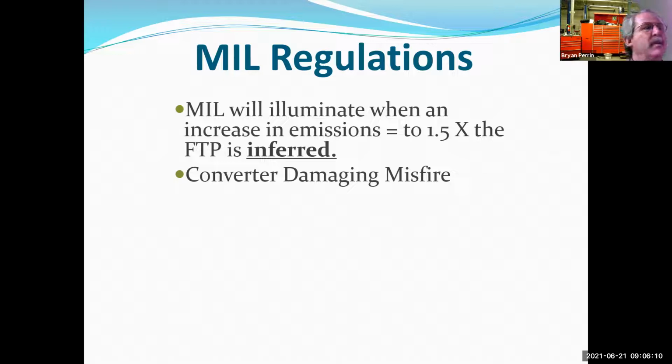So, I have a catalytic converter that melted out. I just ran across a piece of it. It made it 20 miles from brand new to complete meltdown and plug in the exhaust, 20 miles with a misfire. I was pretty proud of that until I talked to another instructor. He had one that did it in 8 miles from cat install to meltdown.